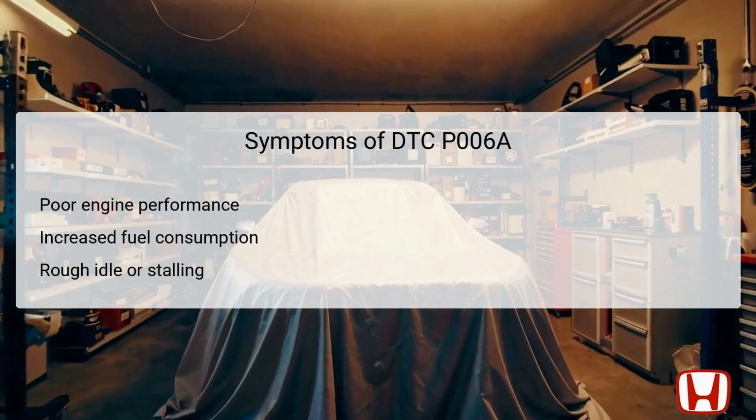When the DTC P006A is present, it typically manifests through several symptoms. One of the most noticeable is poor engine performance, which may involve hesitation or reduced acceleration as the engine struggles to find the right air-fuel mixture.